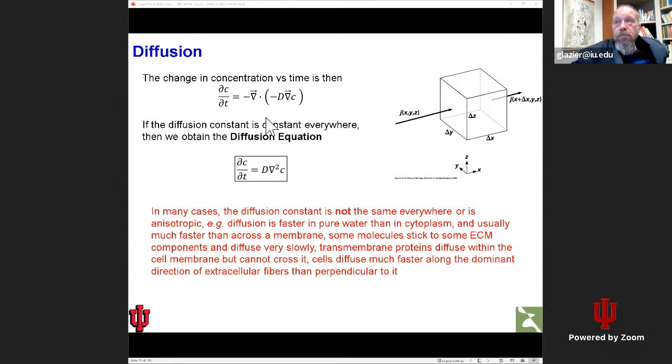However, if the diffusion constant varies in space, we should actually be using this equation up here, where the derivative is taken on the diffusion constant times the gradient. And COMSOL will actually use the second equation, where the diffusion constant changes in space but doesn't have a differential on it. That will give us potentially a small error in our numerical calculations. Usually it's not critical, but it's something to be aware of.